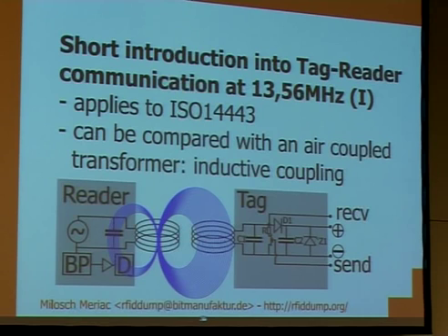You see also the part with D1, C2, and Z1, which gets the power supply part of the signal. Basically, it's a simplified schematic you see here. Normally you have a bridge rectifier, so you get more power. In this case, you only get the upper part of the wave, and it's rectified with D1. It's smoothed by using C2, and Z1 makes sure that the chip doesn't die if we get too near to the reader, because you can get several hundred volts coming out.